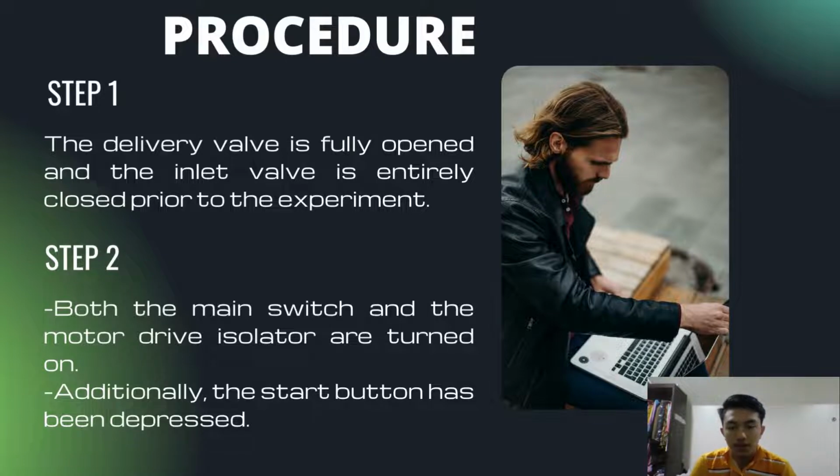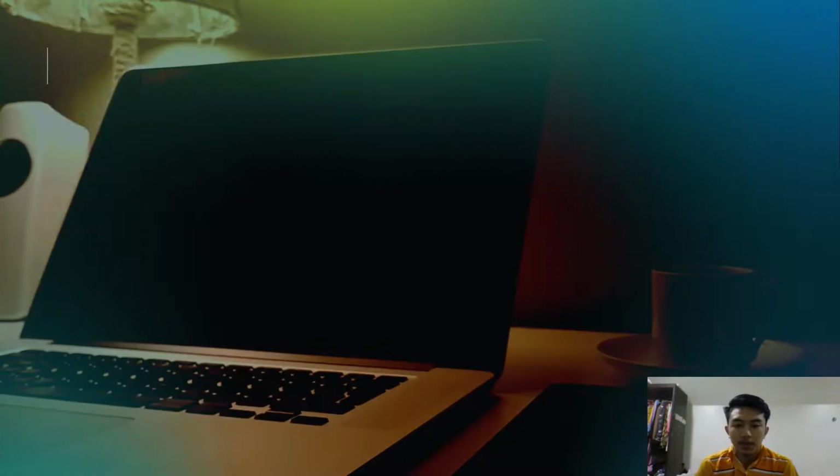And I'm going to continue with the procedure. Step 1. The delivery valve is fully open and the inlet valve is entirely closed prior to the experiment. Step 2. Both the main switch and the motor drive isolator are turned on. Additionally, the start button is pressed.